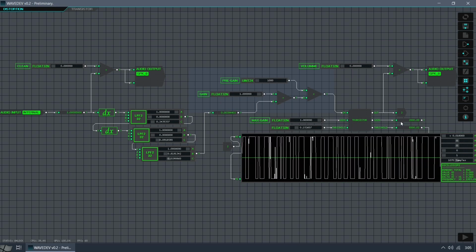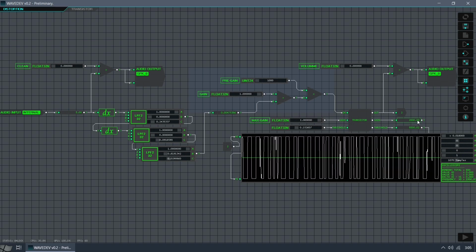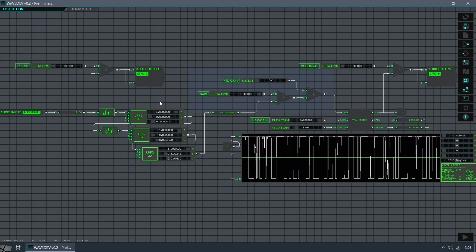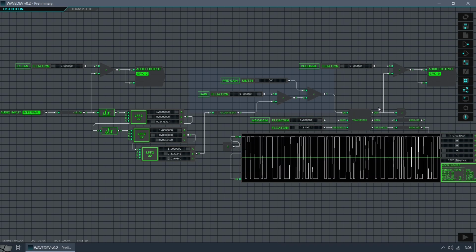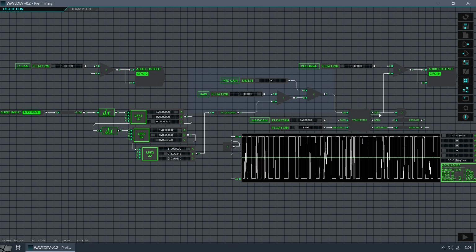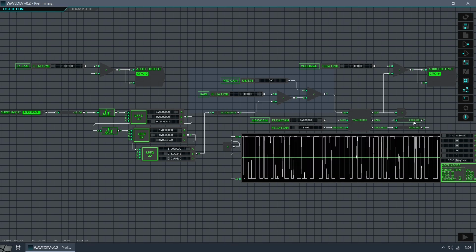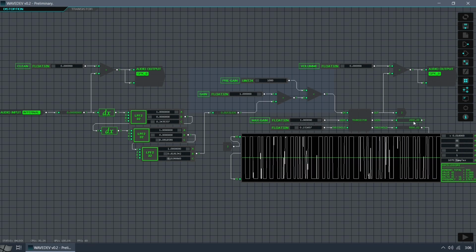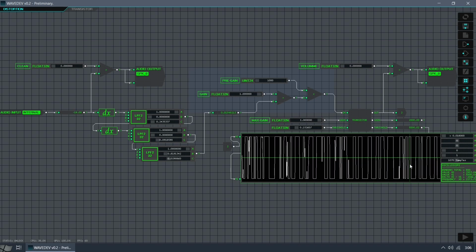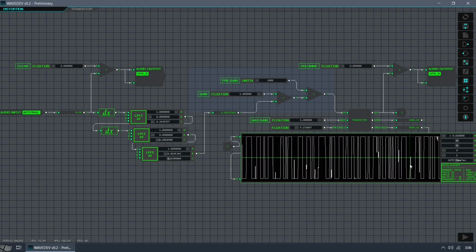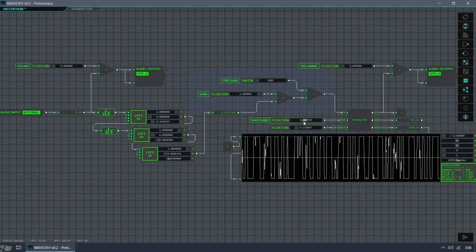If your distortion doesn't sound the way you want with all this gain, then there is something wrong with your filtering, either on the input or the output. Anyway, 2000 is still a value that I will hardly reach with my hardware. Here you can already see how the noise makes our distortion unusable. But let's start with something more modest. A gain of 100 will be fine.